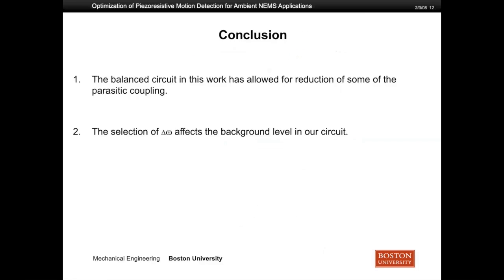Lastly is our conclusions. There are two take-home messages. The first one is that balanced circuits in our work can definitely help us reduce some of the parasitic effects. Second, the selection of the mix down frequency affects the background level in our circuit. Here, I also want to mention that although this mix down frequency is much smaller than the drive and the detection frequency, there is still some parasitic coupling between the signals.